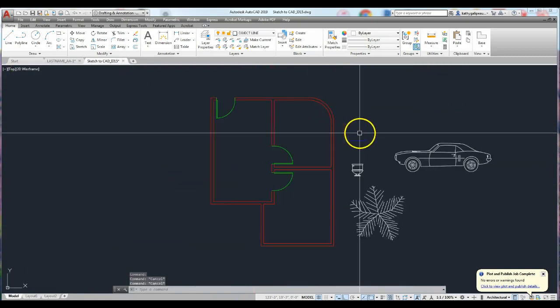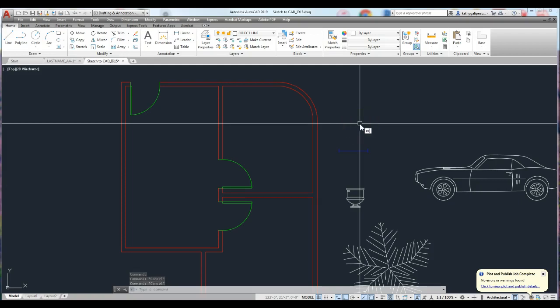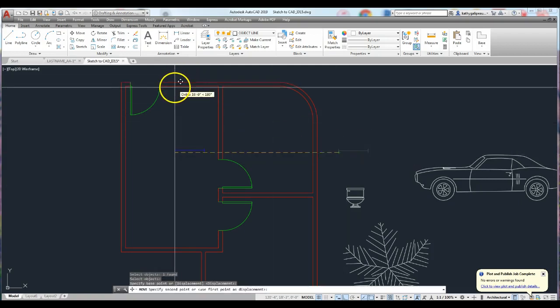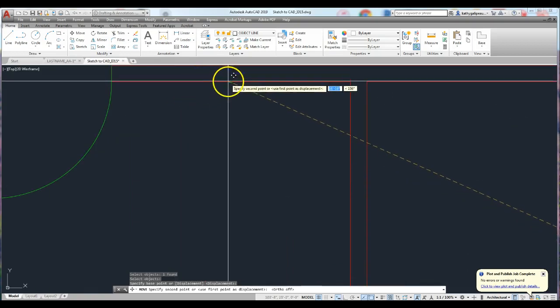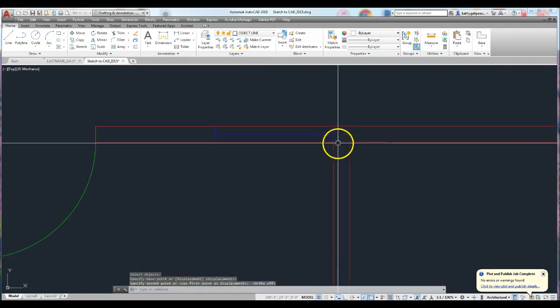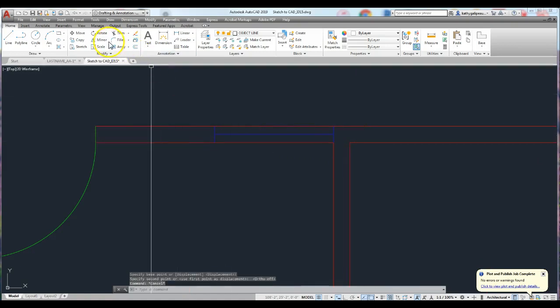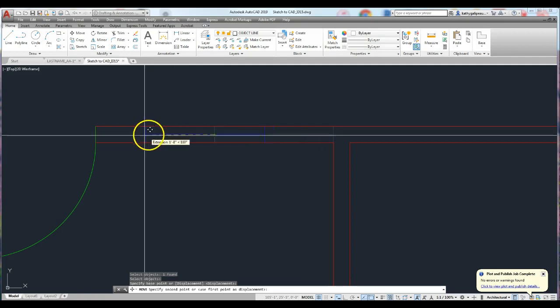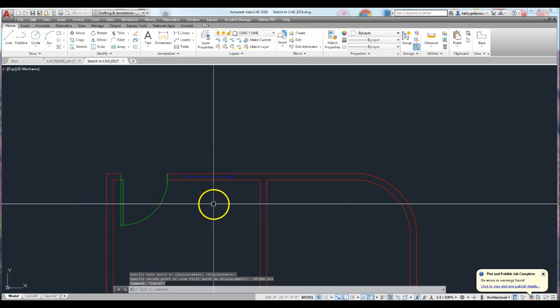So now that we have it adjusted, let's move this window into our plan, ortho off so that it finds the wall, and we'll snap it to the midpoint and then we'll move it. So we don't want it to be encroaching on this wall. Move, select, and drag until we have it. Let's put ortho back on so we have it kind of next to our door there.